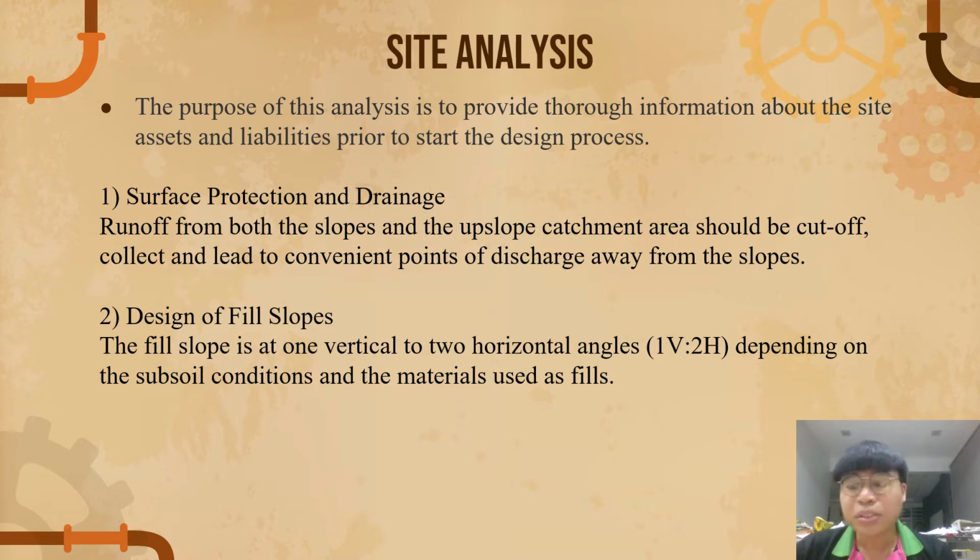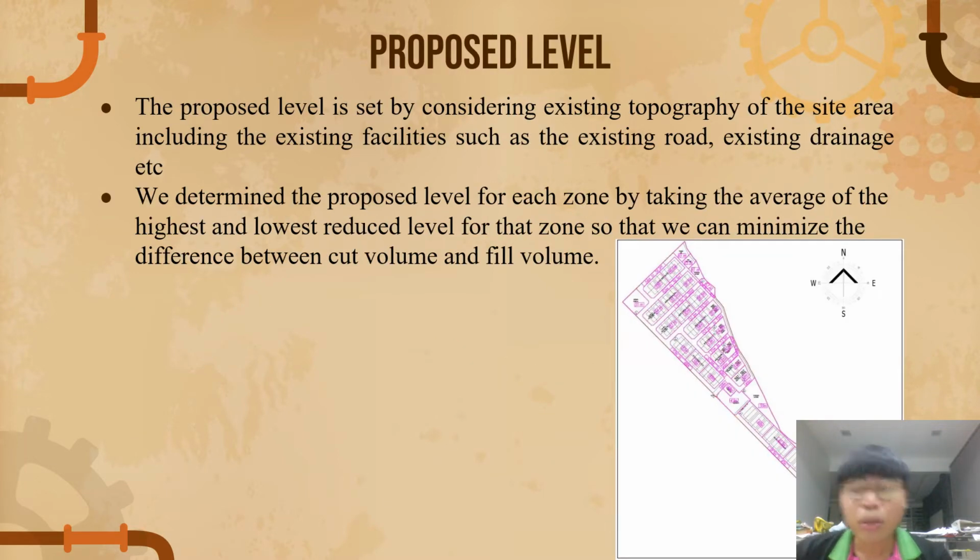The second is the design of fill slopes. The fill slope is at one vertical to two horizontal angles, depending on the subsoil conditions and the material used as fill.